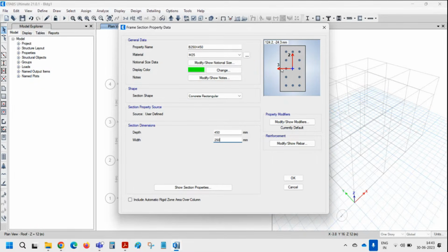Right. So we are looking at the sectional face of the member. So the local one is always along the length of the line element, whether it is a beam, brace, or a column. So local one will be along the length of the member always. 2 and 3 you get to see in the sectional side. Local axes are important because your results will be in terms of local axis. So we should know the local axis orientation as well. Right. So this is sufficient for the analysis.